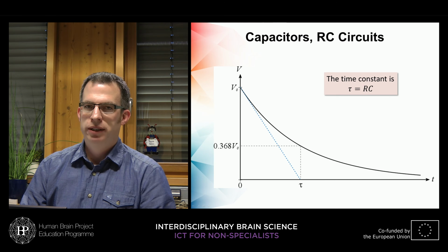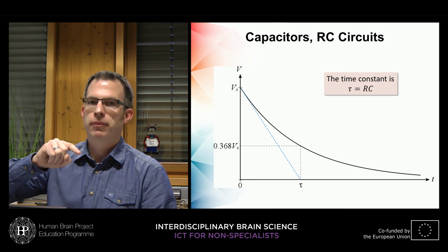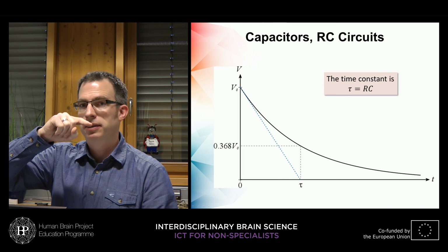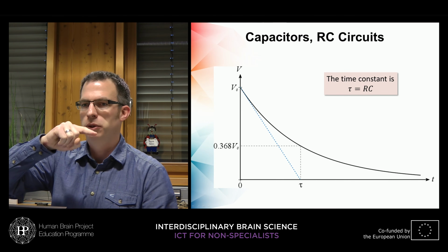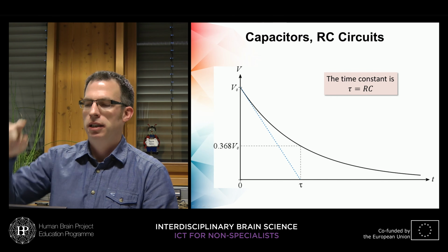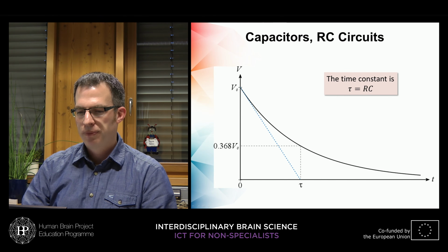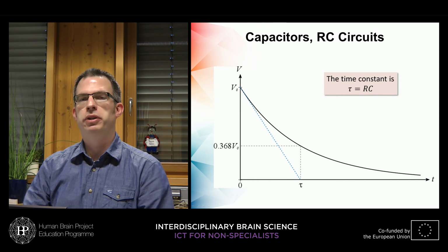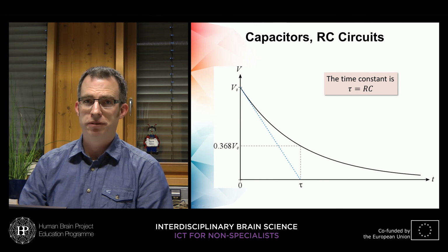And if you, for example, enable a switch, you will never have a sudden increase in the voltage, but it's always, be it as short as possible, an RC curve charging the input capacitance or discharging. That would be what you see here in this characteristic. So that's already all on RC circuits, went quite fast.